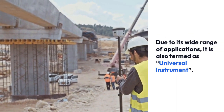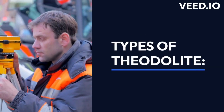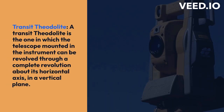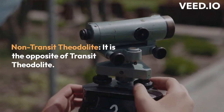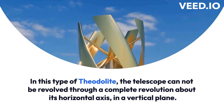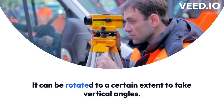Types of theodolite. There are generally 2 types of theodolites. Transit theodolite. A transit theodolite is the one in which the telescope mounted in the instrument can be revolved through a complete revolution about its horizontal axis in a vertical plane. Non-transit theodolite. It is the opposite of transit theodolite. In this type of theodolite, the telescope cannot be revolved through a complete revolution about its horizontal axis in a vertical plane. It can be rotated to a certain extent to take vertical angles.